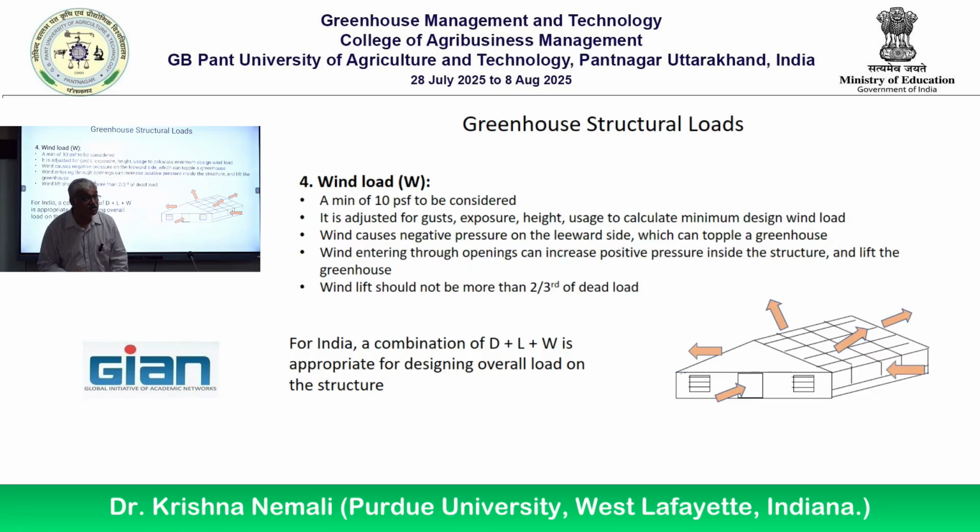If a structure can't withstand this much, there are chances that your structure may be blown by wind, crushed by snow, or when somebody is standing up, it may crush down. That is the importance of this. So important. Okay? When you are designing a greenhouse, you should make sure that the structure can hold up to 45 psf.